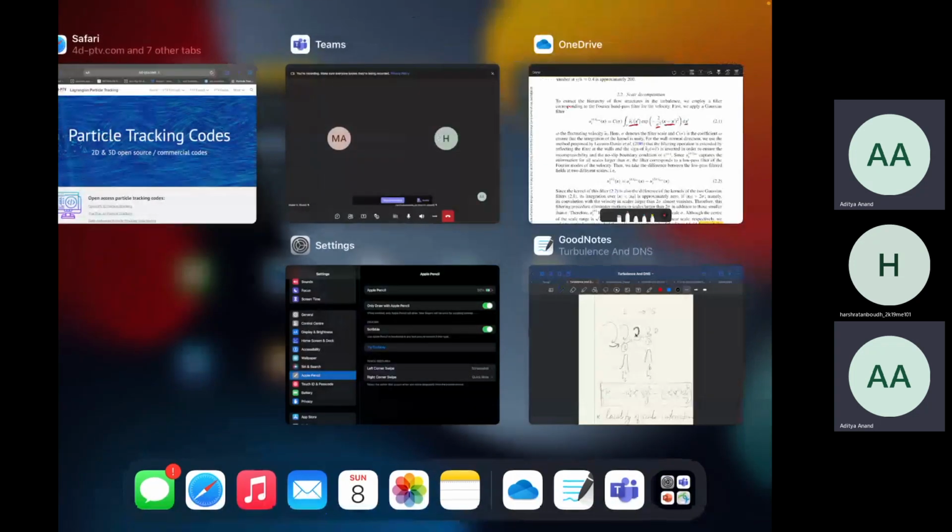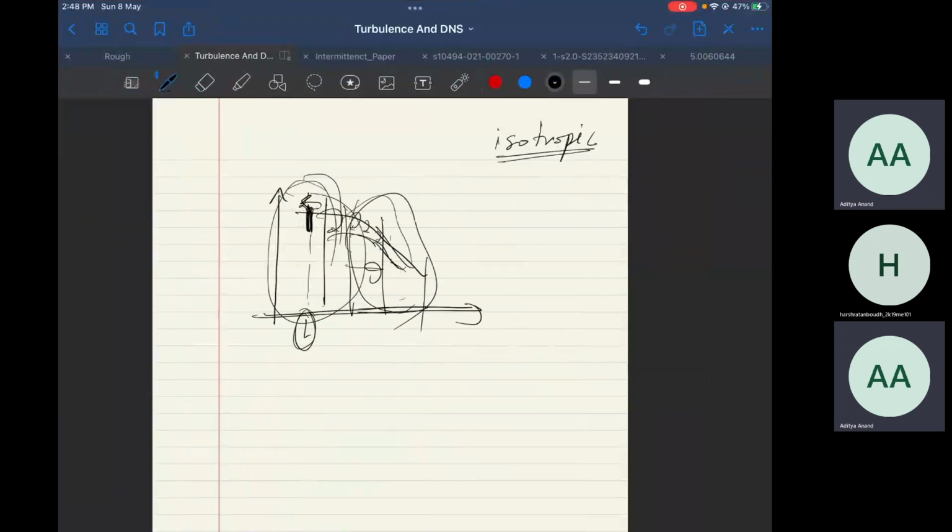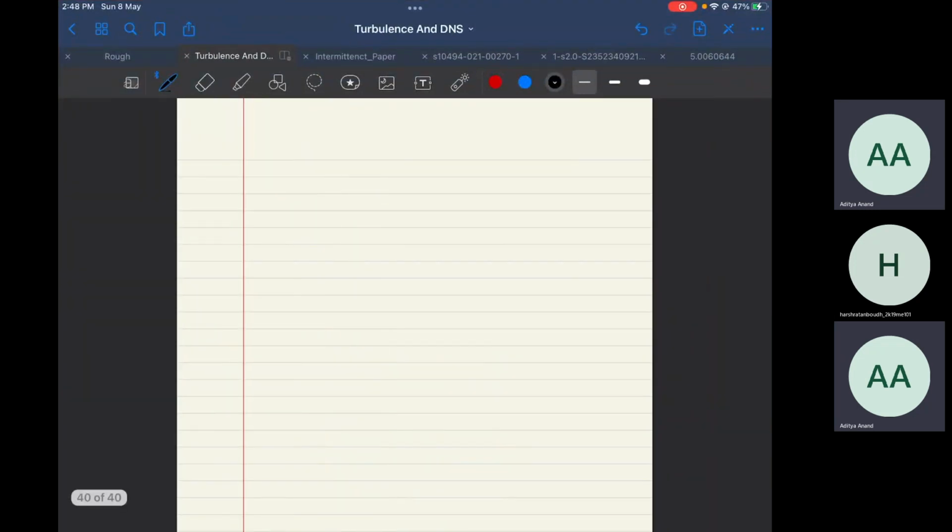Okay, let me do this. So you have your velocity field ux. You can filter this using a convolution integral, or a filter function g. Okay, then you'll get a filtered velocity. This would also be a function of L. You'll have some filter scale L.